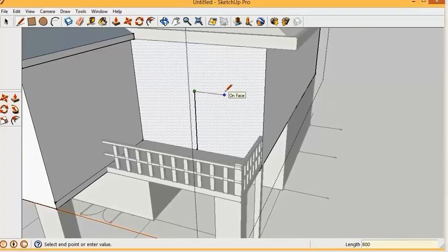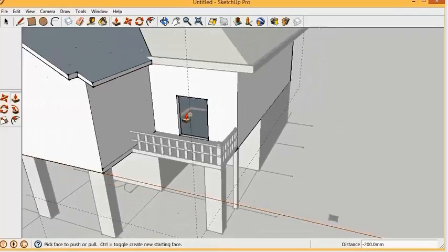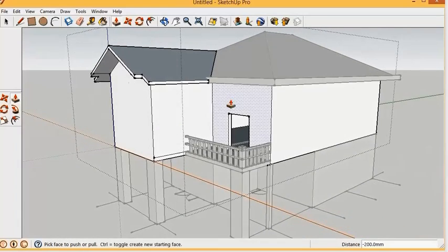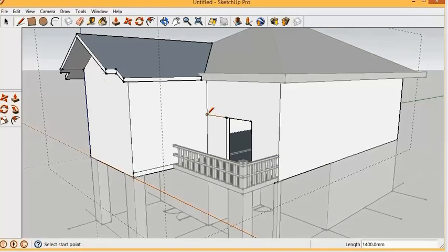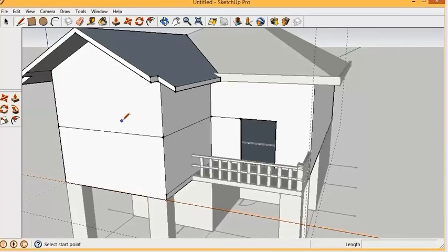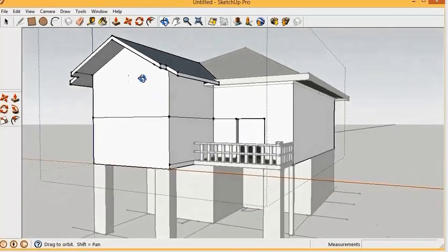As we saw previously, polygons and circles create fundamentally different geometry. One extrudes to a smooth object, the other extrudes to hard edges. Let's take a look at how this works. So I'm going to start with a circle, and notice the circle has a number of sides because it essentially is just a polygon. So I'm going to drag out a circle here, and then let's create an identical polygon. I'm going to type in 24 for the number of sides. Let's just drag that out. Now when we take a look at these, they look pretty much identical.